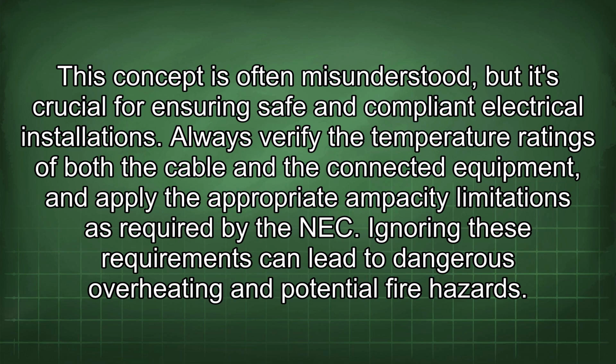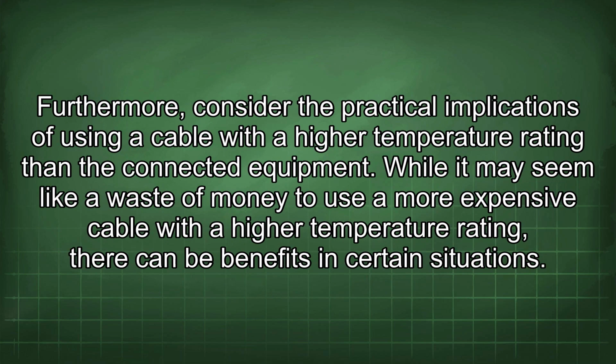Ignoring these requirements can lead to dangerous overheating and potential fire hazards. Furthermore, consider the practical implications of using a cable with a higher temperature rating than the connected equipment. While it may seem like a waste of money to use a more expensive cable with a higher temperature rating, there can be benefits in certain situations.